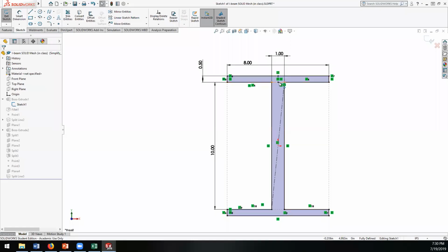Right? So I have things that are on center points. So you want to make sure that you have, I start also in the grid system, so it's kind of on the center there. I have a center point here, so that when I change this overall length, it doesn't just make this part longer, right? It centers it, right?